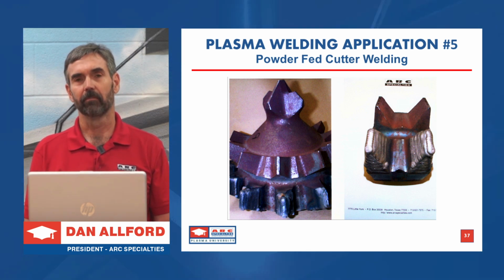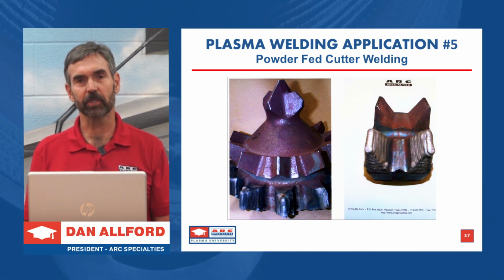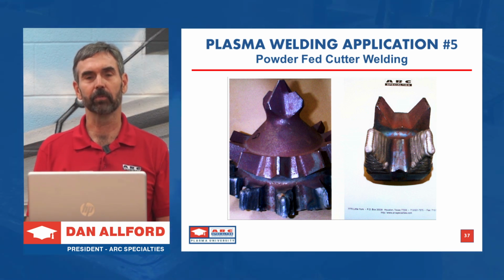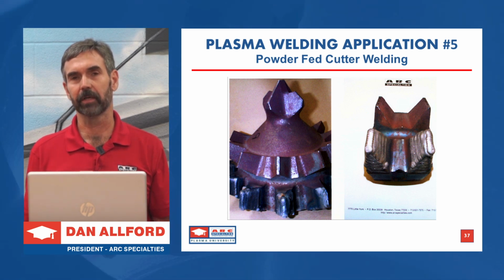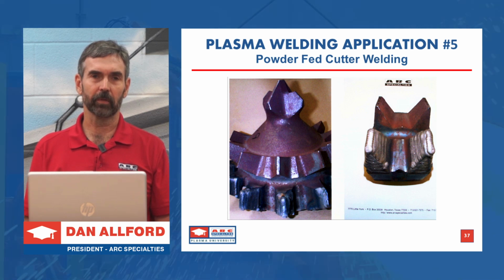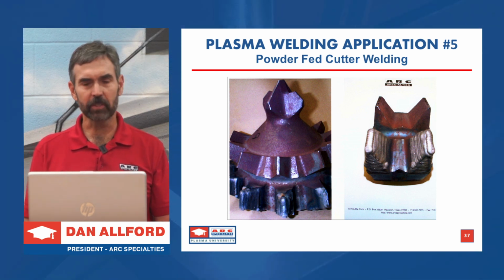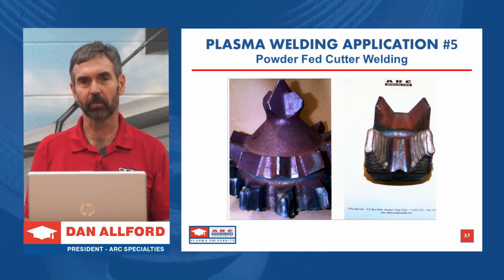The last application was a metal-on-metal wear problem. This one is metal on rock or ground engaging. So you need different filler materials. In this case, we're running composite filler materials. We're running a chrome nickel silicon boron matrix, which is high 50s Rockwell C. And we're running 60% tungsten carbide for the wear mechanism. So these teeth are cutting the oil wells.